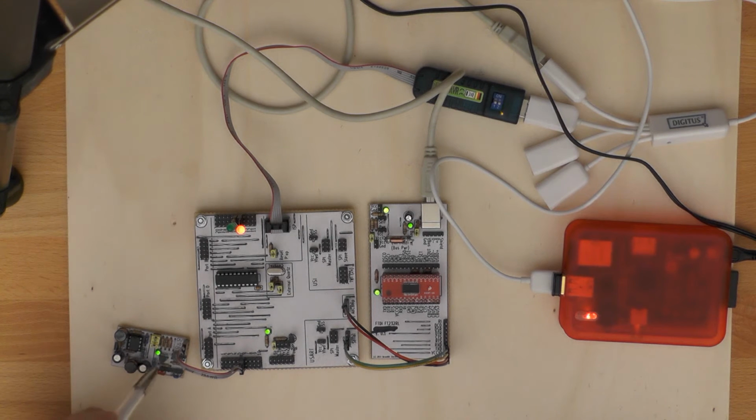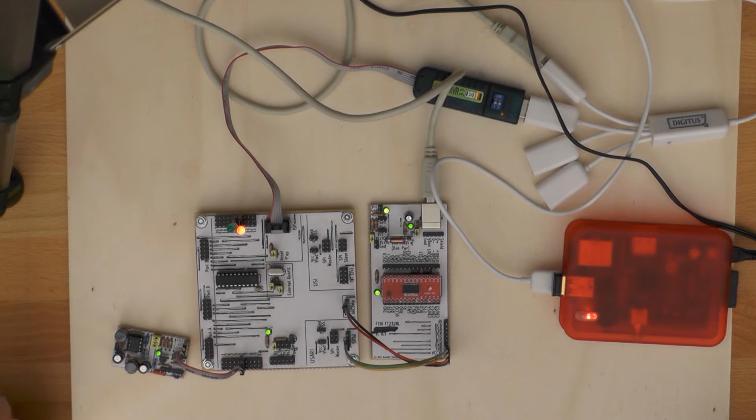It has the generator proper on here and the step-up converter, because I need, for the Avalanche effect to work, at least about 9 volts. I'm using a generator here which generates 13.5 volts. Originally tried with 12 volts, but when I built this, I actually realized if I go for 13.5 volts, I can use some basically E3 series resistors rather than going for E12. So it might be easier to build this from whatever stuff you have lying around. This is what I want to talk about today.